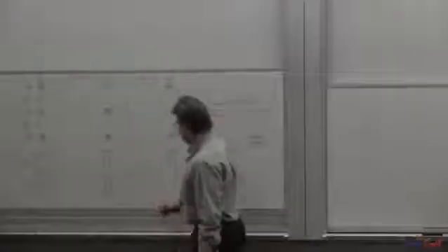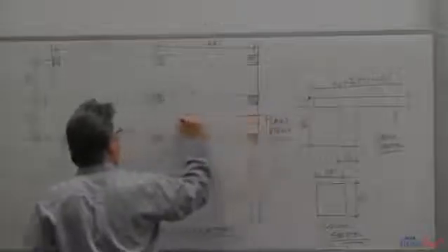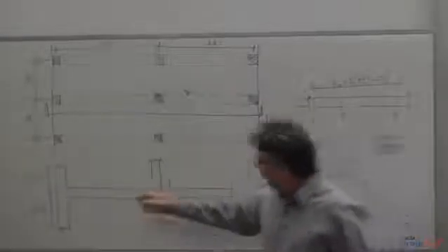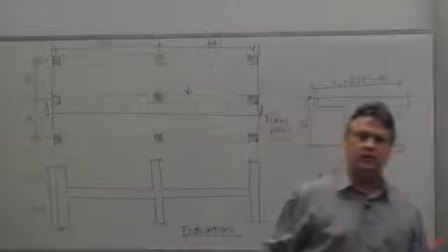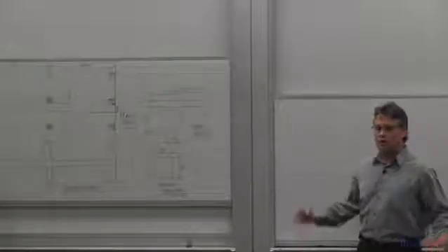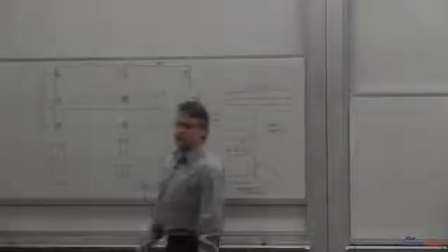This is the elevation. So if I cut a section through here and I'm looking at the beam that I'm designing, this is what it looks like. 11-foot floor heights, 11-foot floor heights. That's very typical for long span parking structures with handicap parking. That gets you the beam, the 36-inch beam depth, plus a little construction tolerance, plus the required height for a disabled van to get in and open. So I didn't just pull this out of nowhere. That number will probably show up on most of the long span parking structures that you ever work on.